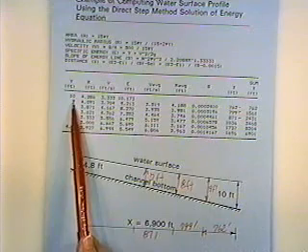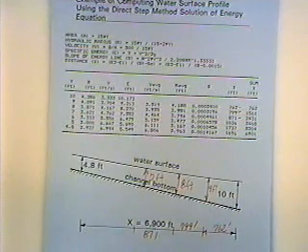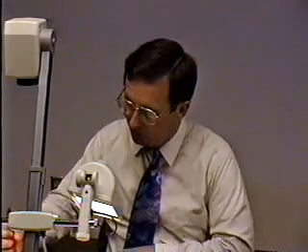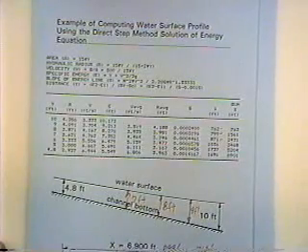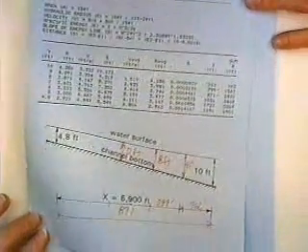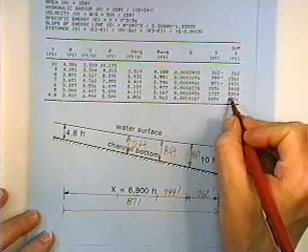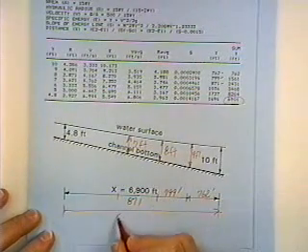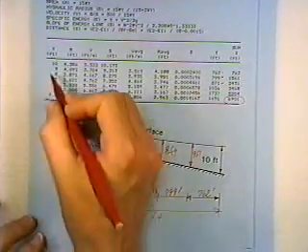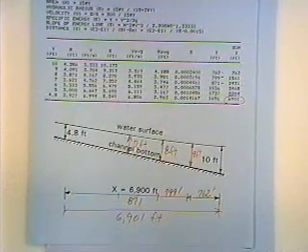So if I make the step size smaller, I get a more accurate answer. And just for fun, I ran this out on a spreadsheet with different step sizes. By the way, the total distance down here at the bottom, all the way from 10 feet to where uniform flow occurs, is this number, the 6,901 feet. And that's using the 1 foot step size.